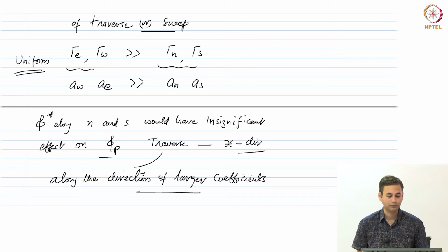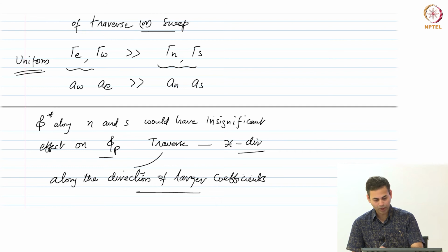The question is, is it a rule for faster convergence, or does it make the matrix better? This is essentially only for faster convergence. AP would also depend on the A north and A south coefficients, but I do not think the diagonal dominance would increase because you have chosen it this way, because you would have a source term. Essentially it is for faster convergence, fine. Other questions? No, okay.